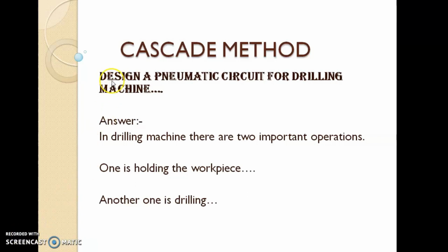Welcome students. In this section we are going to see about the cascade method in hydraulics and pneumatics. In this we take one problem: design a pneumatic circuit for a drilling machine. Actually, in a drilling machine there are two main operations. One is holding the workpiece, another one is drilling.